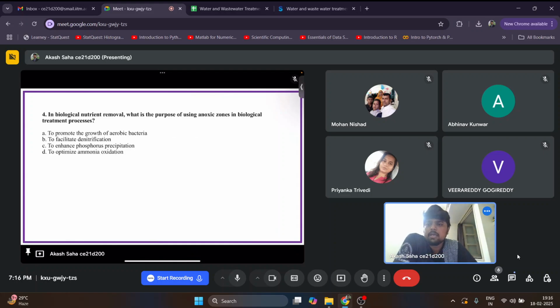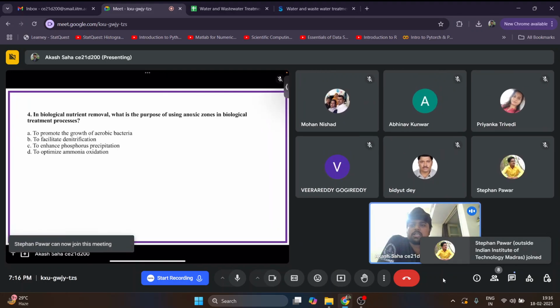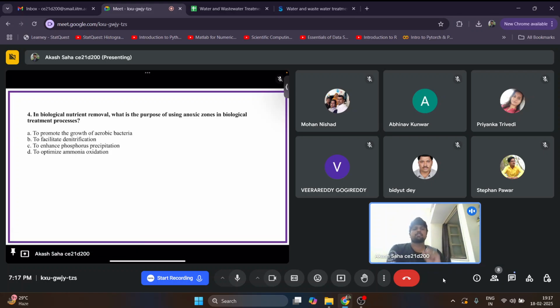Next question. In biological nutrient removal, what is the purpose of using anoxic zones in biological treatment processes? Is it to promote the growth of aerobic bacteria, to facilitate denitrification, to enhance phosphorus precipitation, or to optimize ammonia oxidation? Why do we need an anoxic zone for a biological treatment system? Please give the answer.